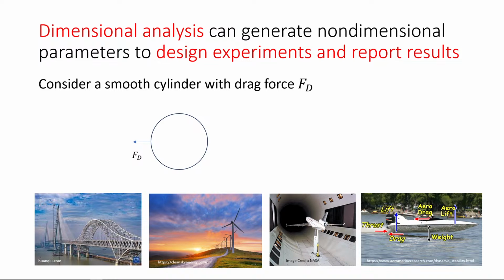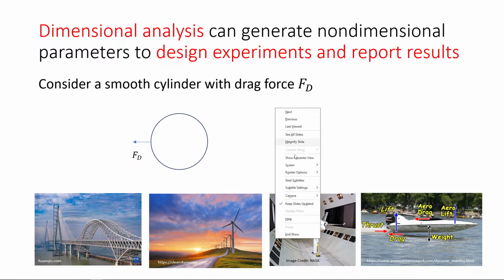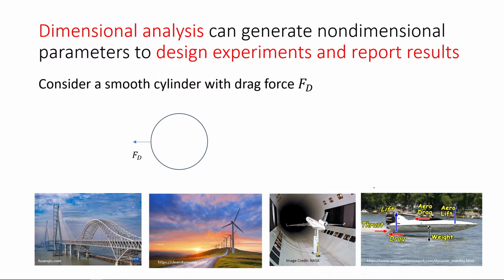Of course, the most obvious factor would be the shape of the object. Let's assume that this is a cylinder, so the shape here would be a circle. So that would depend on the diameter of that cylinder. Basically, as this diameter increases, you would expect your drag force to increase with it. So that would be one factor.